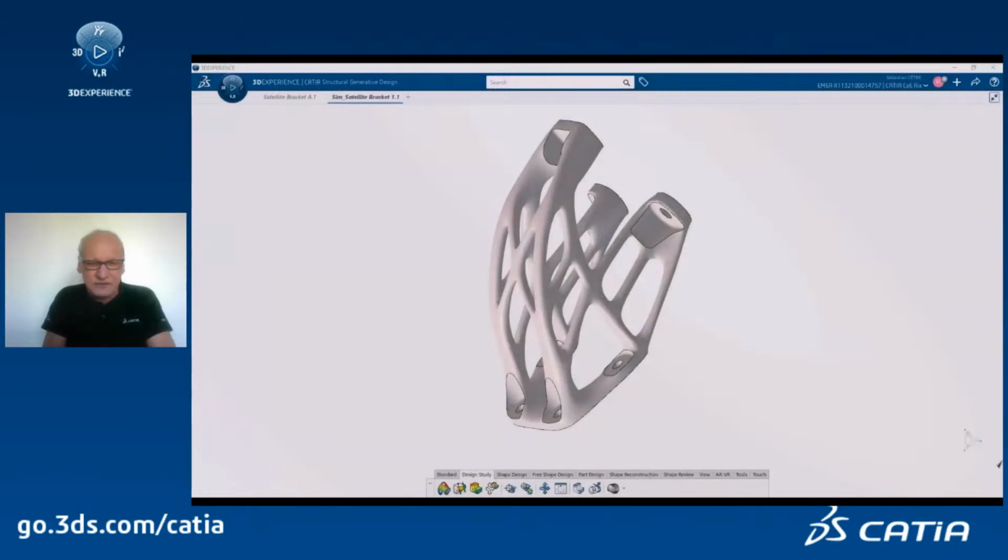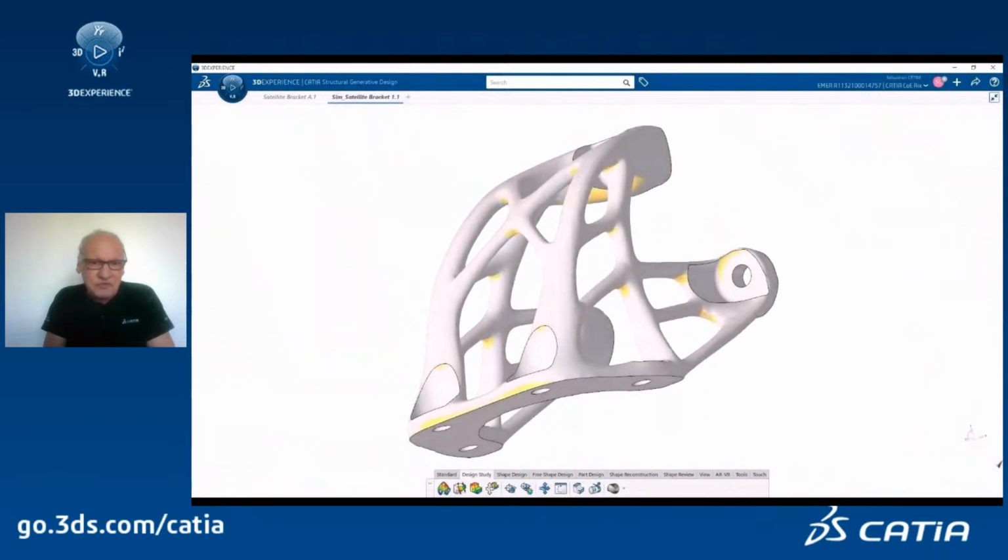And this is what we got. And in the tool, we have also a tool to check if you print it this way, this direction, where will be the supported area. So you see they are displayed in yellow. So very, very limited area, probably no need for support, only at the bottom of the part, obviously. Okay, that's it.